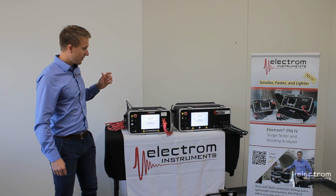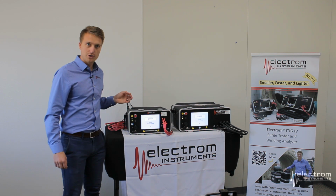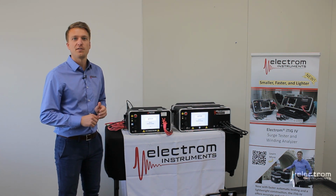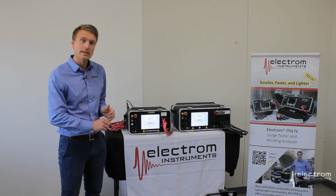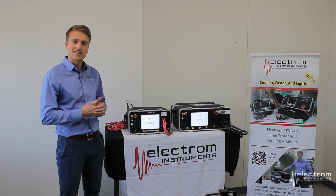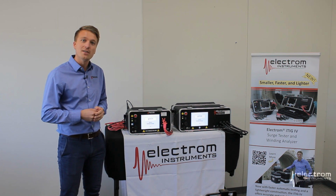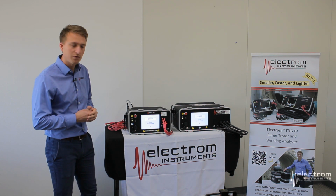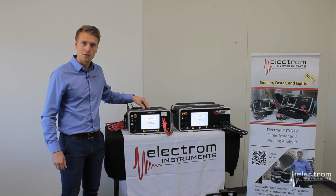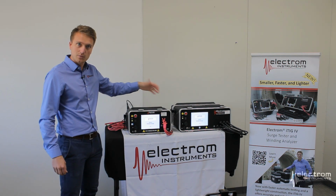Now that we have our tester connected to a motor, we can run a quick demonstration. We will be testing a 460 volt 3-phase concentric wound stator. The concentric wound stator has obviously a different type of layout of the coil, so we expect to see some fun differences in the surge waveforms. We will be using the 4 kV for this demonstration, but the operation on the 6, 12, and 15 will be the same.